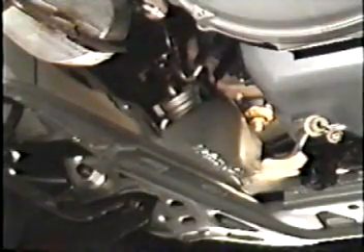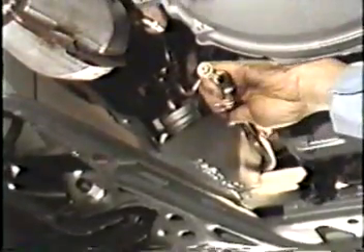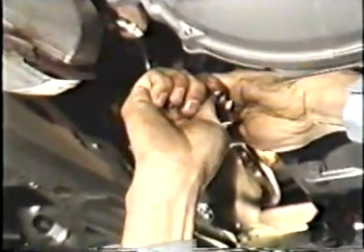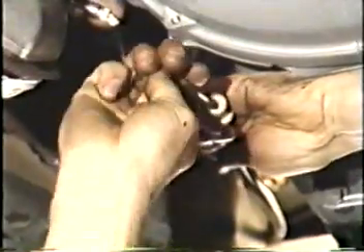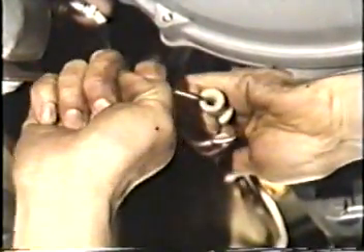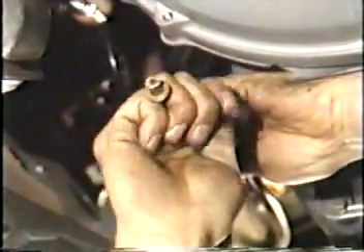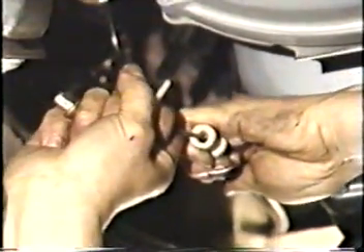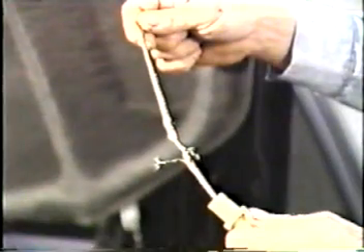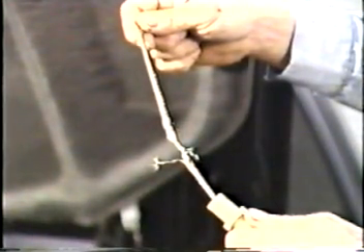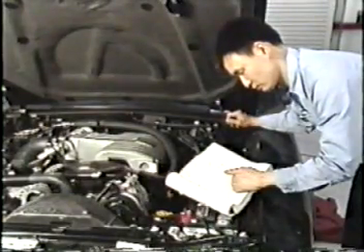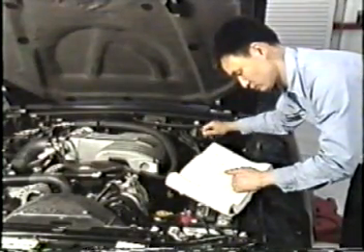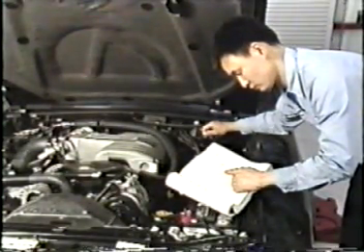Now, test the cable by pulling it back and forth from the release arm end. The clutch cable should move with almost no effort at all. Modern cables are pre-lubricated at the factory and shouldn't need lubrication in the field, but there are two common reasons that a cable might stick. The cable can become frayed, like this one, or it can become kinked if it's misrouted. Once the cable has been kinked, it can't be reused.